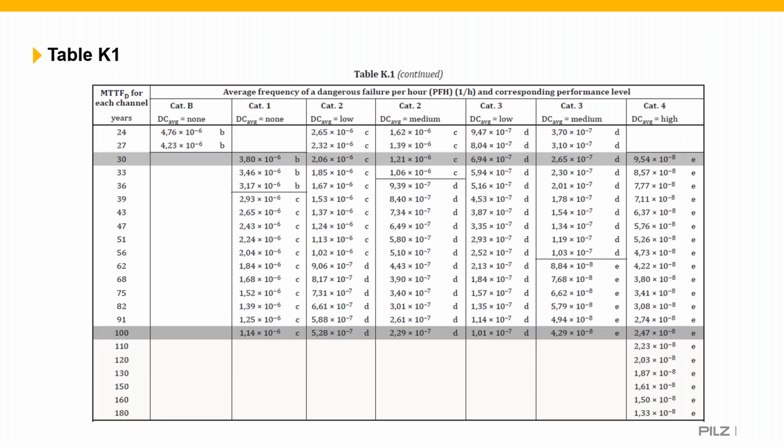And you'll see from that that the maximum performance level you can achieve then is C. So without any diagnostic coverage, that is the maximum you can achieve. So you've got to consider this in your design and understanding of safety-related control systems.